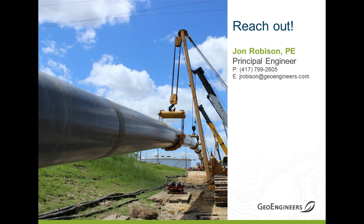Okay. What types of pipe material can be used for the direct pipe method? Currently, it's steel only for jacking pipe. Again, similar to the question about diameters, we have done several projects where we installed HDPE or other kinds of pipe within a casing. But as far as what's capable of withstanding all the installation stresses, right now it's steel. And what is the minimum depth for a direct pipe?